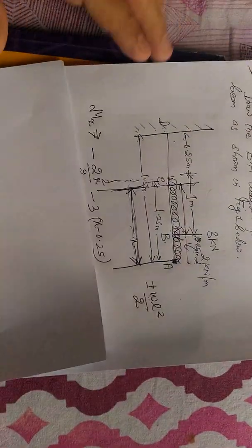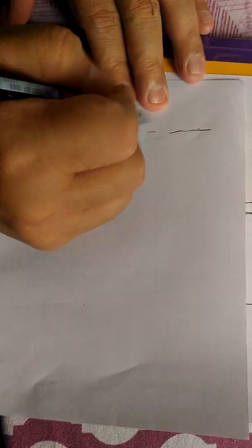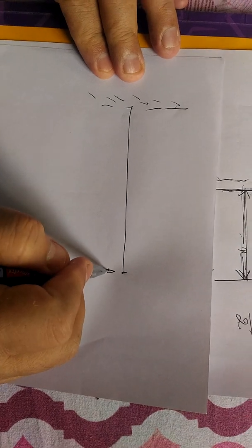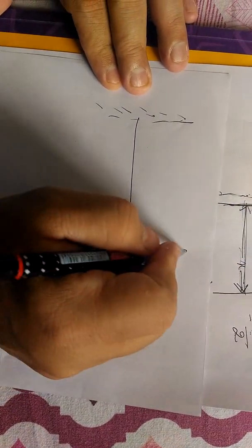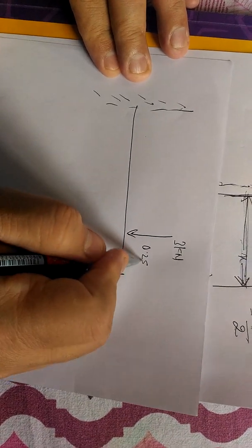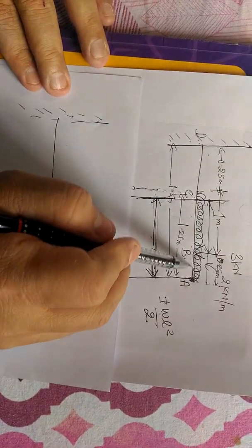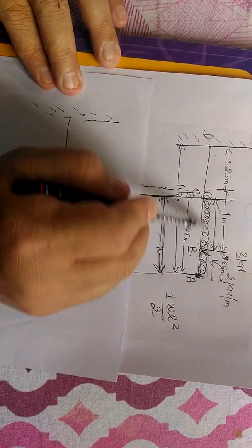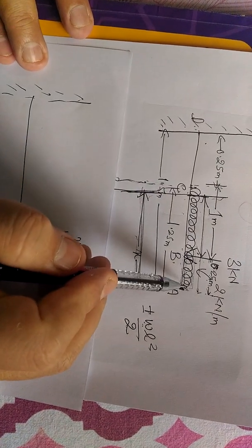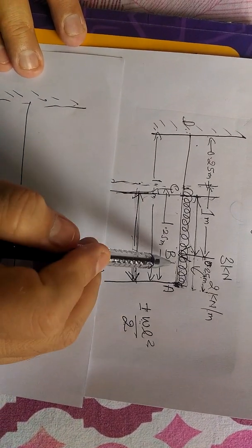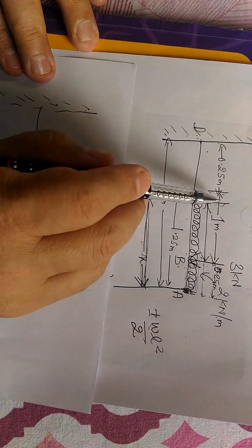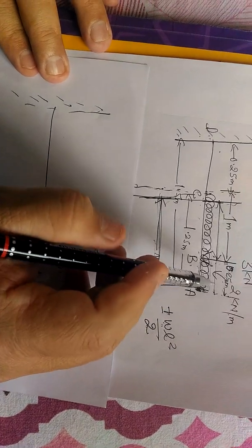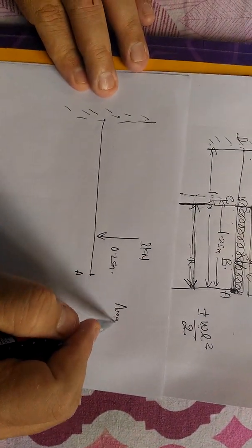So first we'll convert this into point load. So 3 kilonewton, 0.25 meter, and in order to convert this into point load, as I have explained in earlier videos, we'll have to find out the area of this rectangular portion, that is UDL. The height is same, so this is a rectangle, so area of this rectangle is height into length. Height is 2 kilonewton per meter, that is intensity of loading, and length is 1.25.